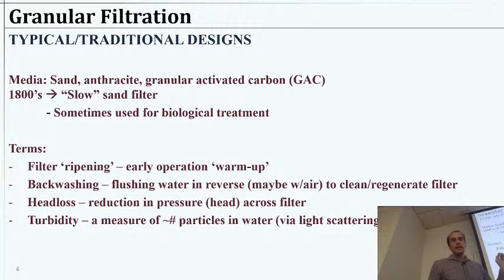Okay, and that would be like you put a bunch of water on there and then it probably stays on the sand for a couple days' time for the slow sand filter. We're looking at the hydraulic retention time. So nowadays we're sending water in much faster. We're going to talk about some of the rates of loading water onto the filter and the rates of backwashing, things like that. So as we talk about the filter operation, we're going to talk about filter ripening.